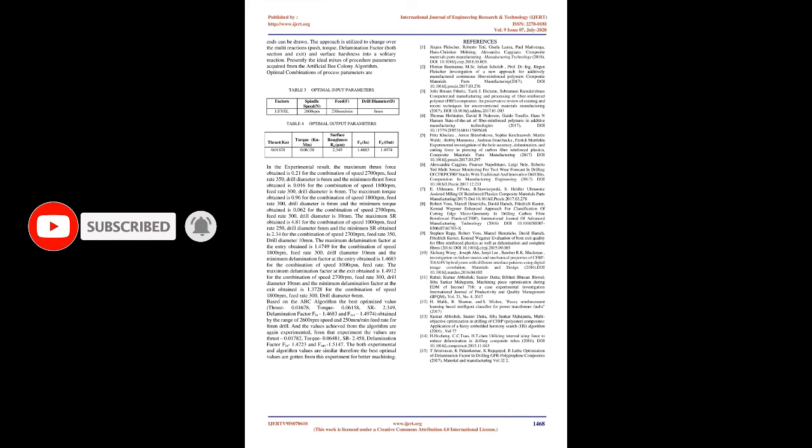10 mm. The maximum SR obtained is 4.81 for the combination of speed 1000 rpm, feed rate 250, drill diameter 6 mm, and the minimum SR obtained is 2.34 for the combination of speed 2700 rpm, feed rate 350, drill diameter 10 mm. The maximum delamination factor at the entry obtained is 1.4749 for the combination of speed 1800 rpm, feed rate 300, drill diameter 10 mm, and the minimum delamination factor at the entry obtained is 1.4683 for the combination of speed 1000 rpm, feed rate.